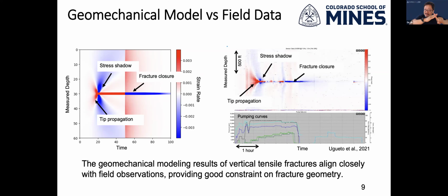However, you'll see as we keep pumping and pumping, we're seeing a lot of additional fracture intersections, with a span much longer than my stage length, hitting later in the stage. And we see this repeatedly across all the early stage signals. So this is very strange, because we're growing hydraulic fracture within this 200 feet of wellbore, but why are we creating a fractured zone at the monitor well 1,000 feet away that is 400 to 600 feet wide, right? So are we creating something like a fan-shaped fracture? That doesn't make sense. So that's abnormal number one.